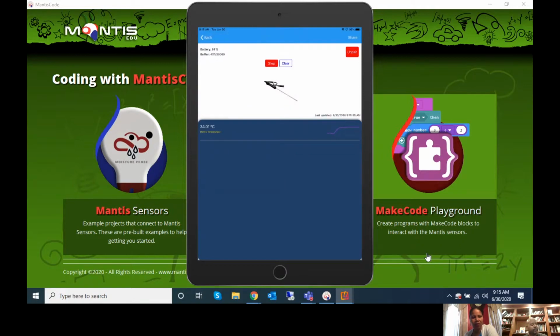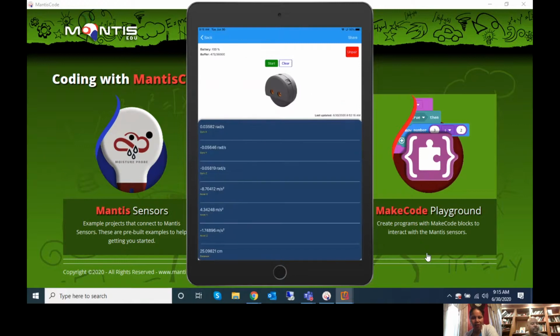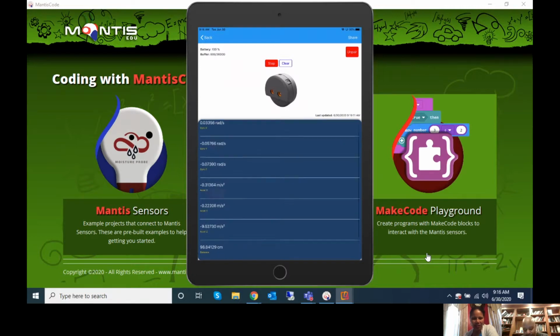So that's one example. Now, notice that while that's working, I'm also connected to this device, and this guy is called the MODI. The MODI is a gyro and accelerometer and distance sensor. So think about it as like a Fitbit on steroids. So notice how I'm going to sit it on its back right now, in my hand. And notice that if I look at the Z acceleration, it's roughly negative 9.8, representing gravity, right? If I flip it over, you notice it's at positive 9.8, right?